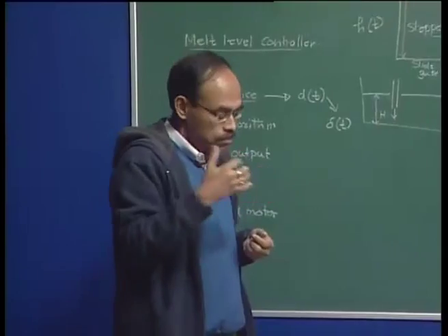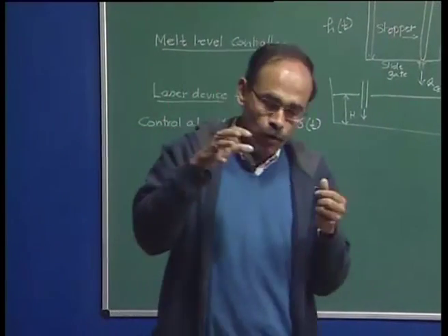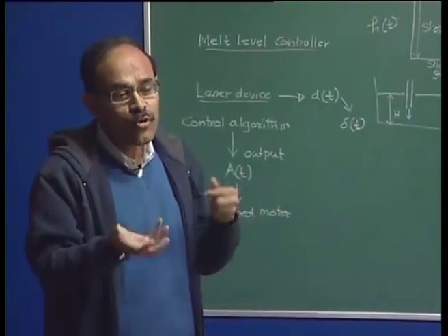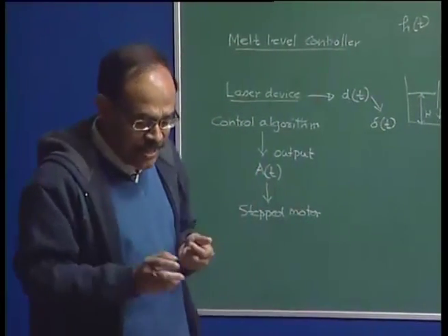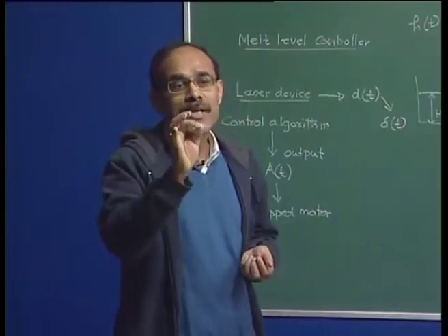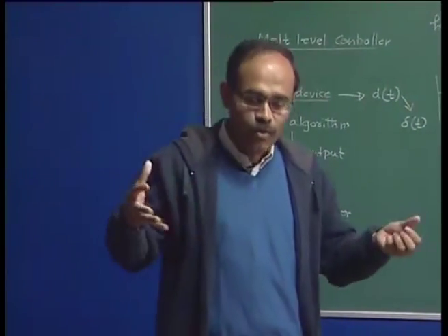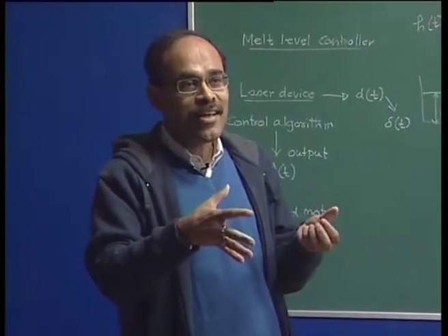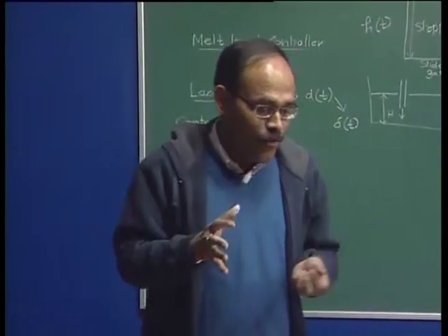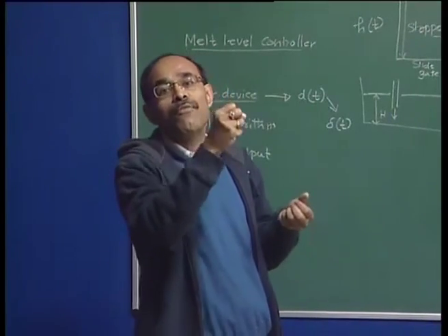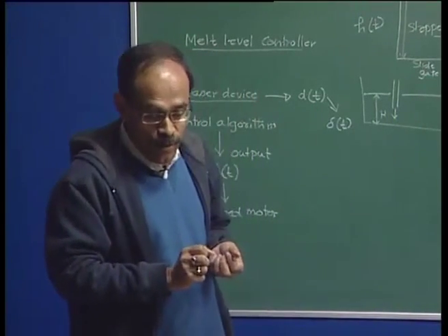And following ladle furnaces, we can go for vacuum degassing, and subsequently we can go for inclusion modifications through injection metallurgy and so on. I have also mentioned to you very categorically that the more secondary steel making operations you incorporate in your steel making circuitry, the amount of effort is going to increase, and as a result the cost of the final steel produced is going to increase.